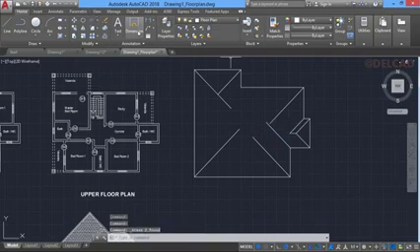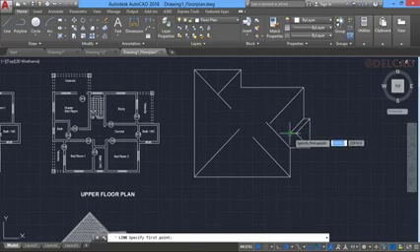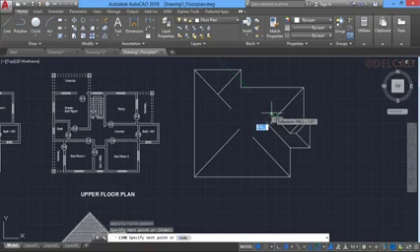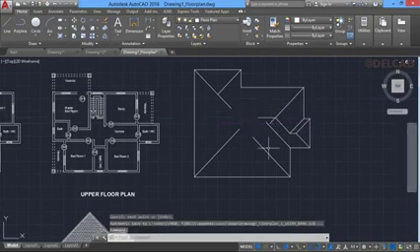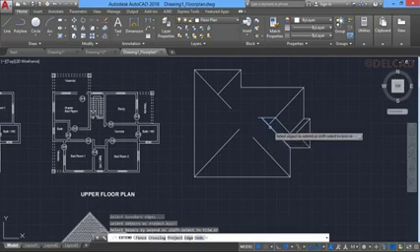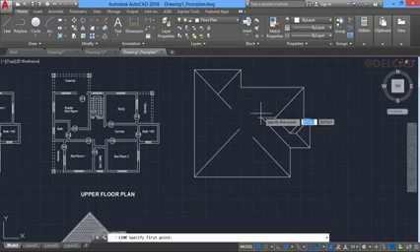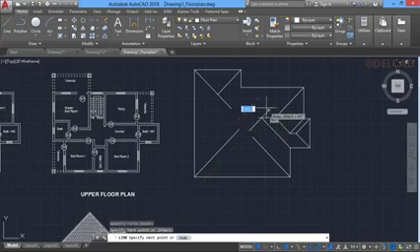So erase. Again, we're going to use the line tool, and at this point we'll draw another line which will go at 135 degrees. So it's going to meet this line exactly at this point. Now at that point you draw another line which will come very direct at 180 degrees. So select line and draw towards this side at 180, and then we're going to extend this line. So type EX to extend this line at that point, and then use the line command again. So select line and draw towards this side at 135 and stop somewhere.